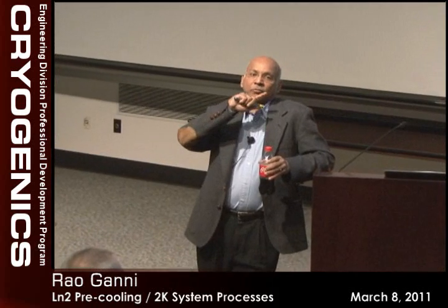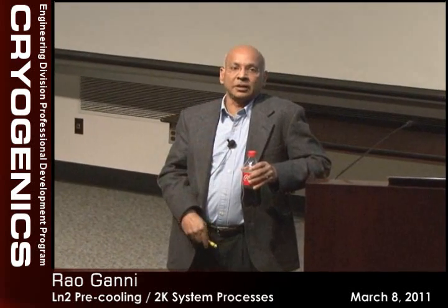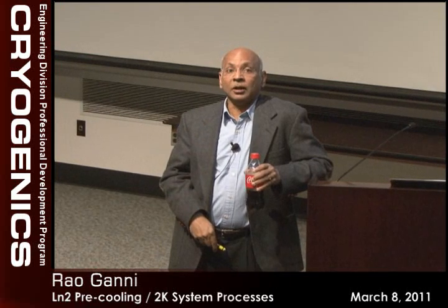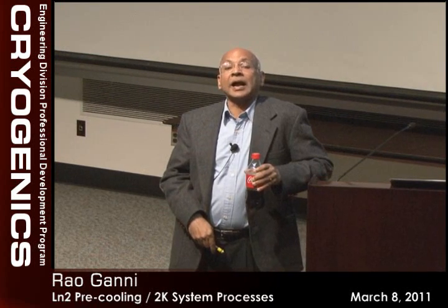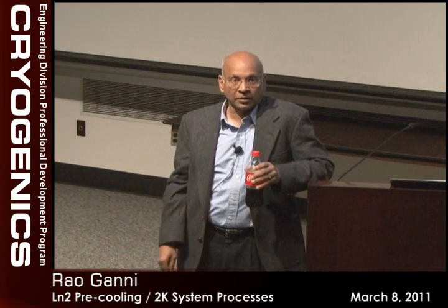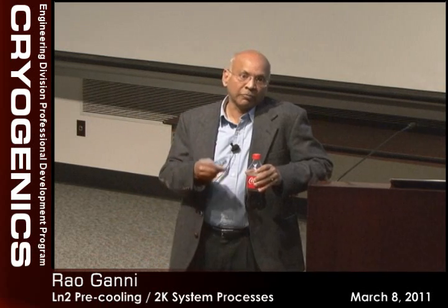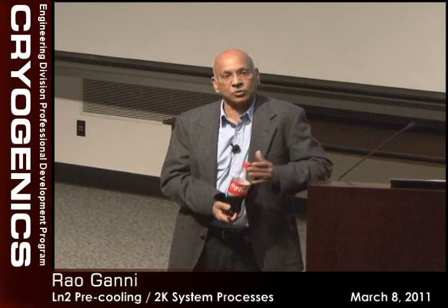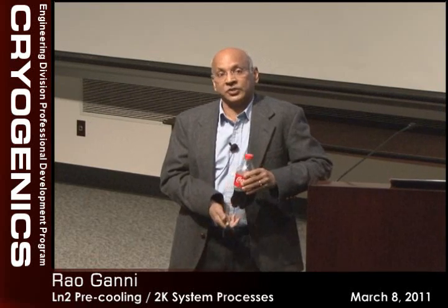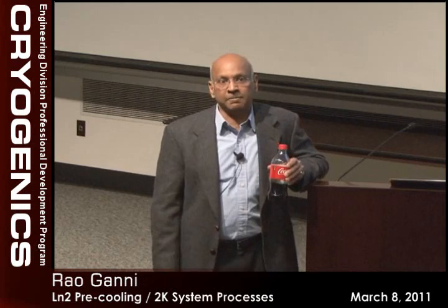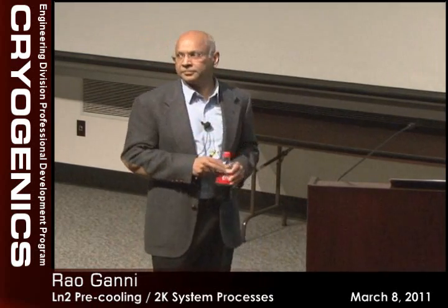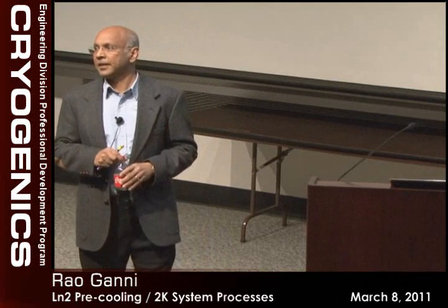That's what we thought, but the other problem is the 60 hertz dependency. At 60 hertz it was dropping so low. That's a different problem than not having a good power factor overall. Because the motor is too big, we can rationalize that, since twice the size makes the overall power factor poor. But 60 hertz, we can figure that out. Why the 60 hertz dependency? Anybody else? One more quick question.